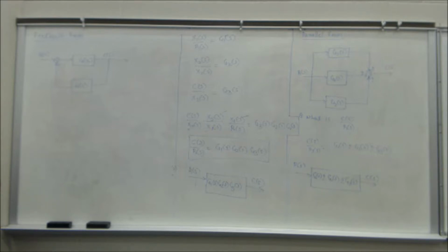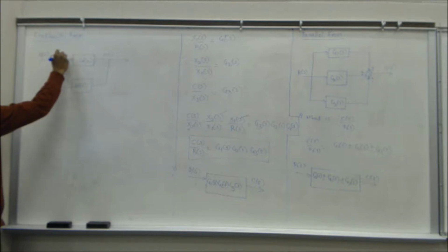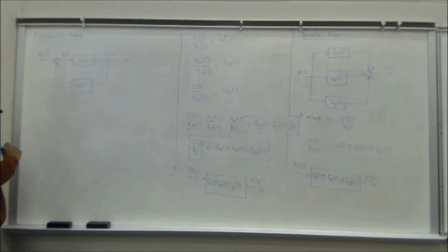This is slightly challenging, okay? And you're going to encounter this a lot. So please pay some attention. So the way you're going to go about doing this is, if you're given such a block, the first thing you're going to introduce is an error signal, okay? E of S. Error signal, yes.